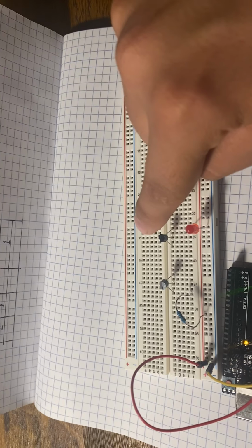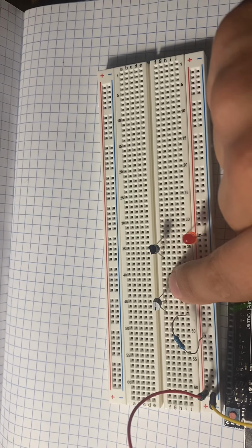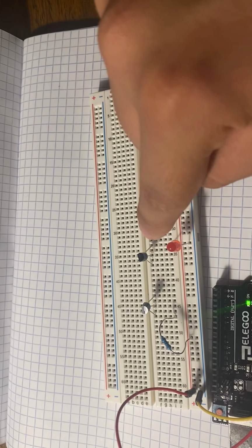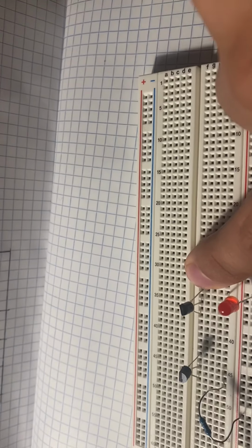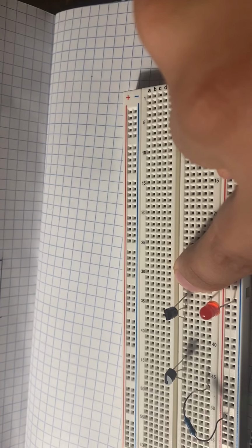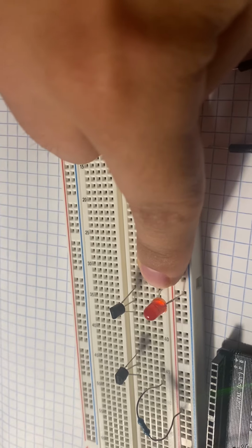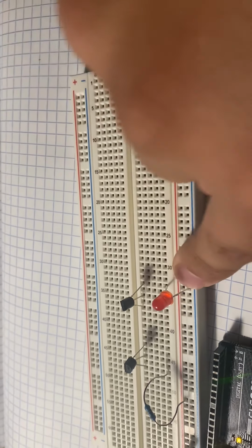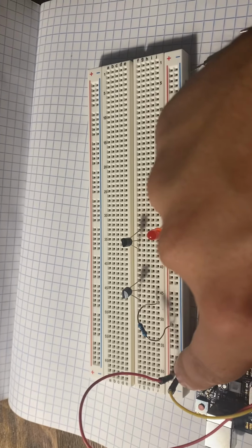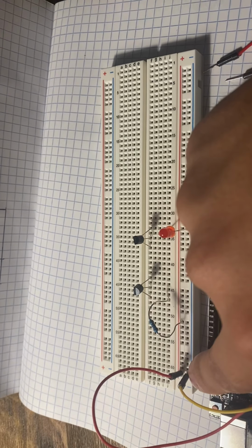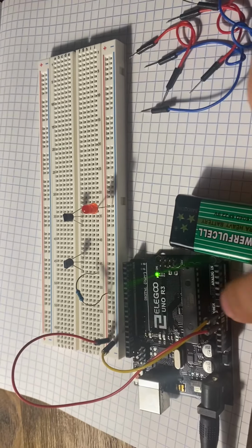Now, the second transistor here is aligned with the first one. And then the component of this transistor, which is the emitter, I have aligned with the long leg of the LED bulb. Now, the shorter leg will be connected to my ground, and then aligned with, that's right, the ground cable, the jumper cable that eventually runs back over here to my controller board.